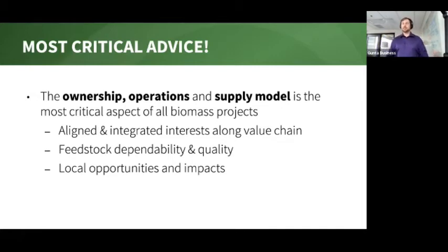Feedstock dependability and quality. I would say this is probably number one. I liked my first one because it represents the operational issues, but feedstock is specifically the root cause of all operational issues of biomass. A lot of times it's because the technology that was picked for biomass requires a high grade wood fuel. The community picks it, but they think that they could have a wide inclusion of waste wood, and then they realize that they can't. And then they're screening, and then it just causes issues.